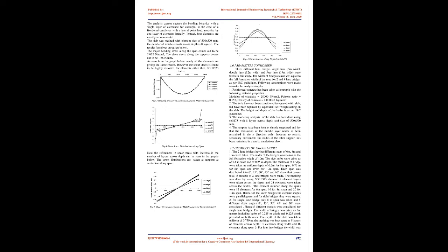V, Poisson's ratio, equals 0.152. P, Density of concrete, equals 0.000025 kg/mm3. The bridge was analyzed for the self-weight only. Types of elements used as per ANSYS Element Library: SOLID 45, SHELL 63, SOLID 73, SOLID 186. SHELL 63 has both bending and membrane capabilities, both in plane and normal loads are permitted.